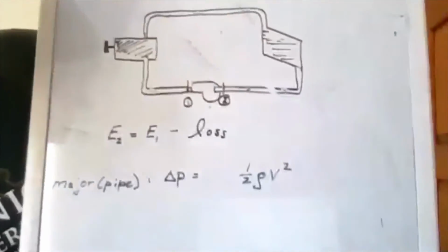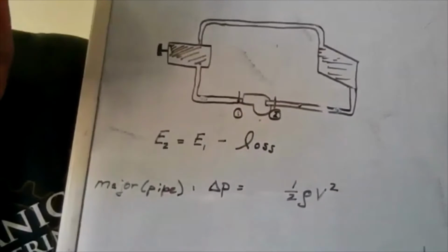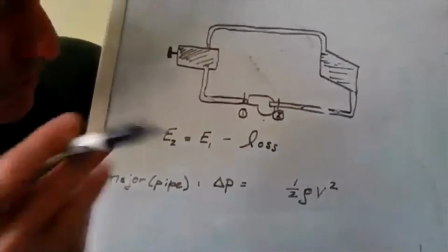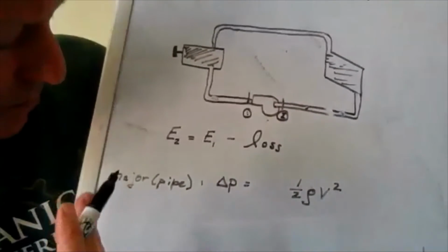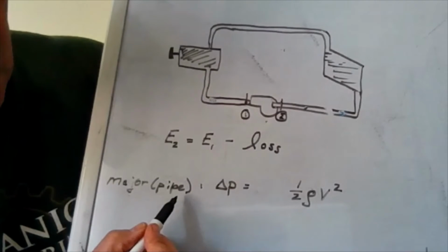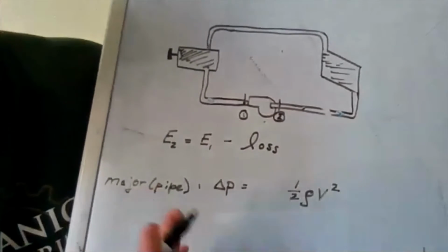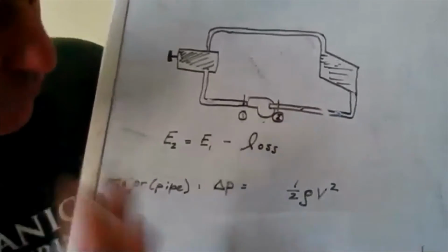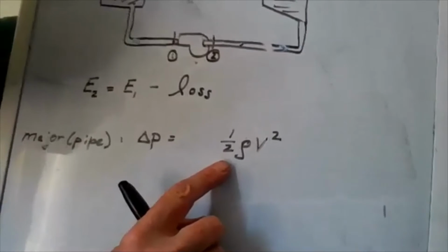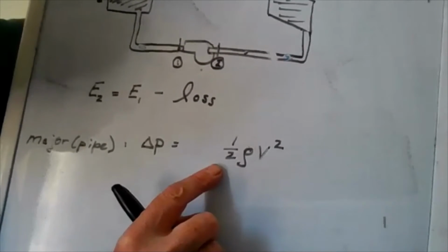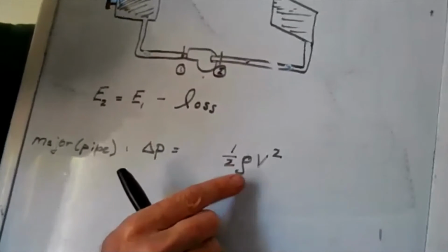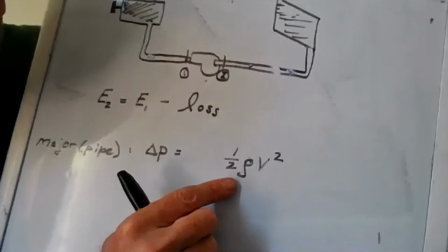So what we just did has to do with the way we think about losses in fluid systems. There's two most common ways we do it. So going back to what we did in chapter 8 earlier, we actually went over major losses, which are oftentimes termed pipe losses, and we got it in terms of pressure loss. So going back and reminding you really quickly, once again, what we can do is we can do this term 1/2 rho v squared. That's termed the dynamic pressure, and we can think about the loss as being related to how much energy the fluid has expressed as pressure.